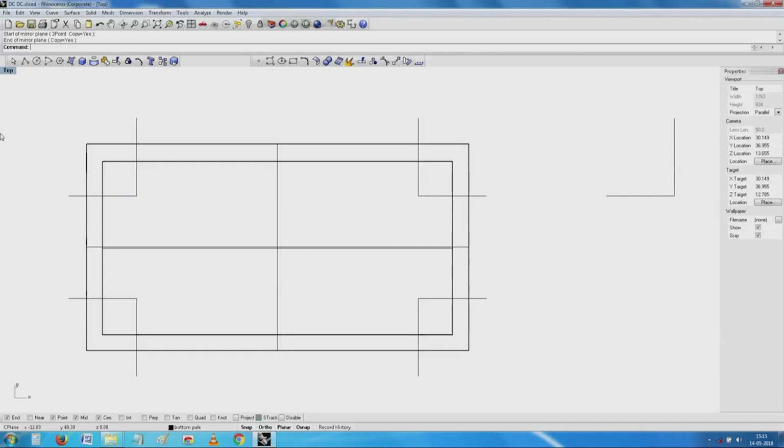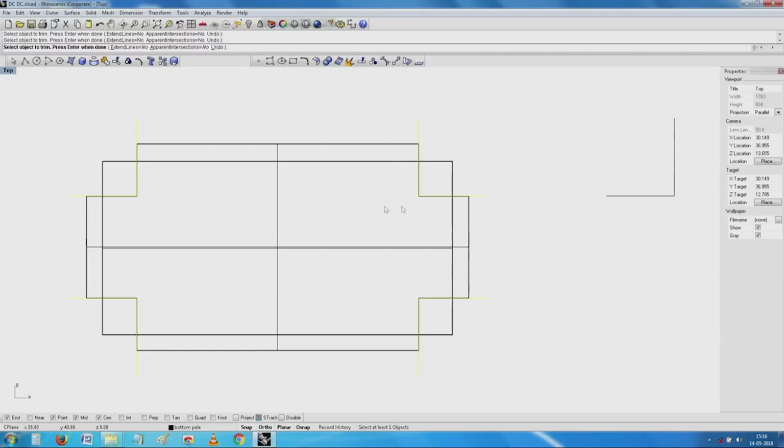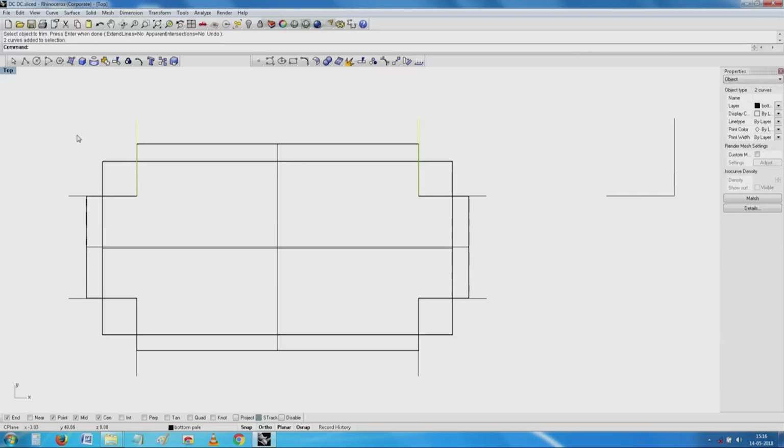I will now go here and try to cut the surfaces completely. I select all these objects which I can use for notching off. Notch, corner, corner, corner, corner. You see here, I have a nice heat sink where the corners are beautifully taken care of,